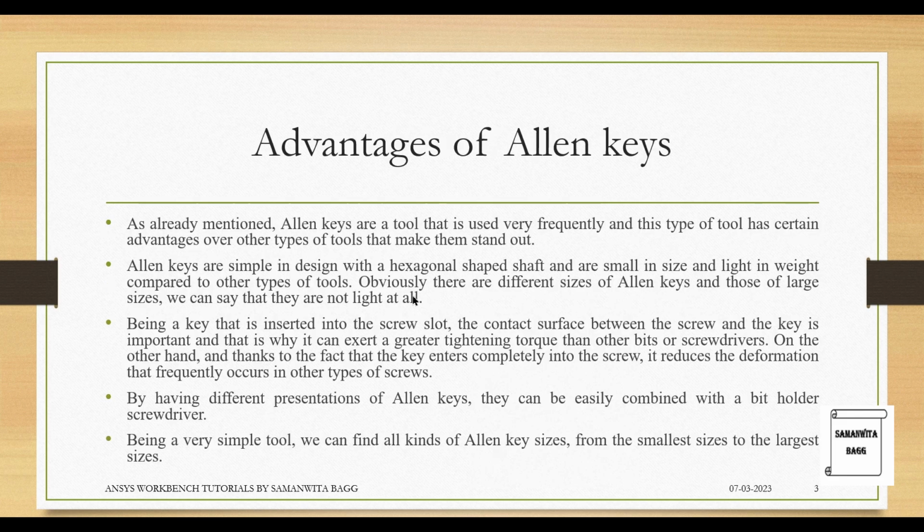There are various advantages of Allen keys. As already mentioned, Allen keys are a tool that is used very frequently, and this type of tool has certain advantages over other types of tools that make them stand out. Allen keys are simple in design with a hexagonal shaped shaft and are small in size and light in weight compared to other types of tools.